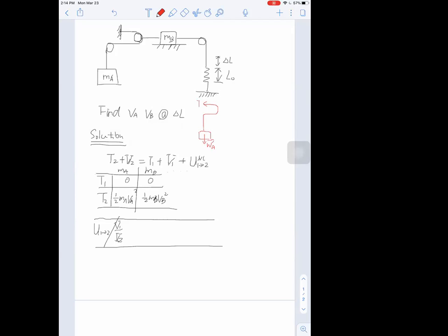And on the other end of the pulley is connected another block. It has a weight force WB. And there's another rope wrapped around the pulley, goes down, and there's a spring force Fs pulling this rope down. At the pulley, remember we have two pulleys here to tighten up the rope. So there should be reaction force R2 and reaction force R1.